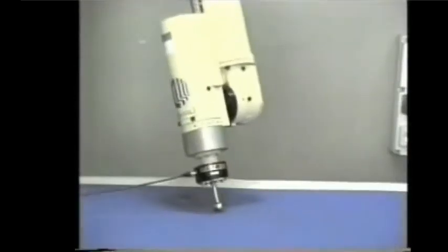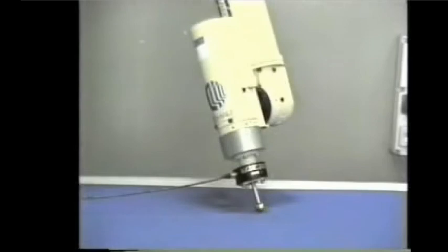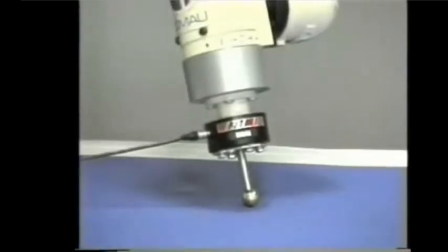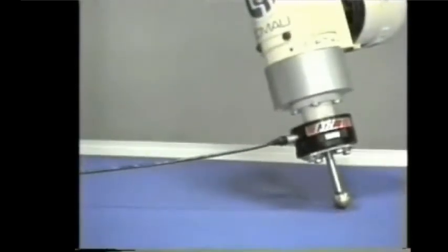And the same is achieved while in contact with the surface, so the tangential velocity is being controlled, the normal velocity is controlled to zero, and the orthogonal velocity on the plane is controlled to zero, and the normal force with a force sensor, as you can see here, is regulated to a desired value.